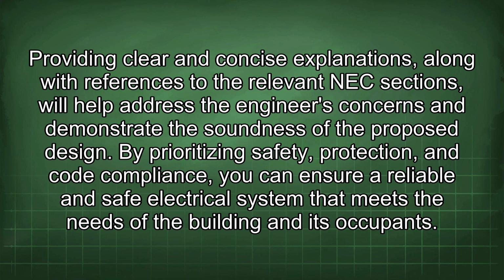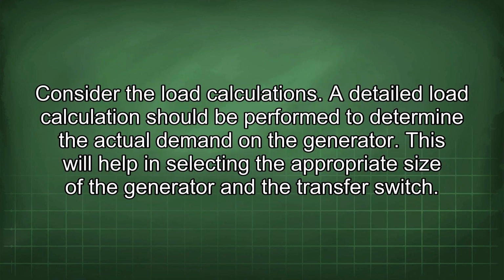By prioritizing safety, protection, and code compliance, you can ensure a reliable and safe electrical system that meets the needs of the building and its occupants. Consider the load calculations. A detailed load calculation should be performed to determine the actual demand on the generator. This will help in selecting the appropriate size of the generator and the transfer switch.